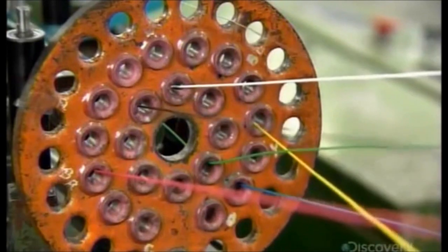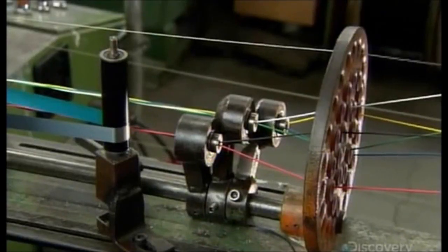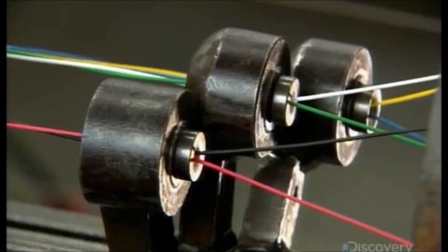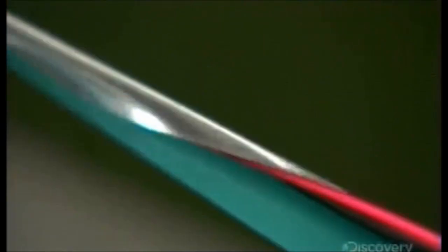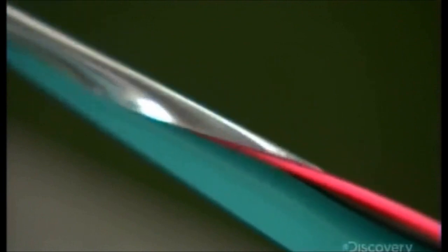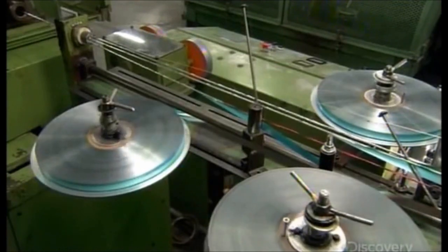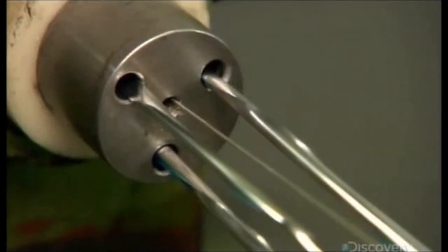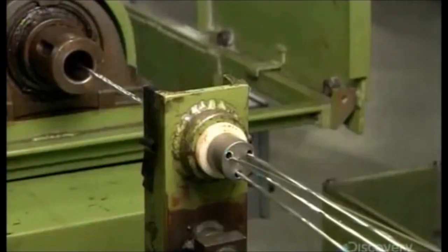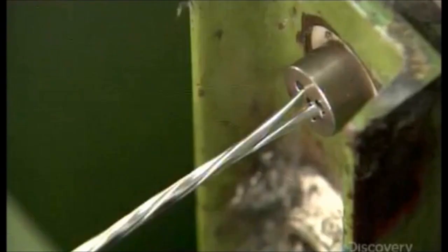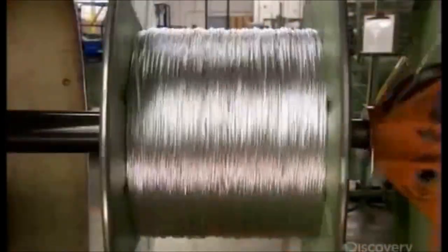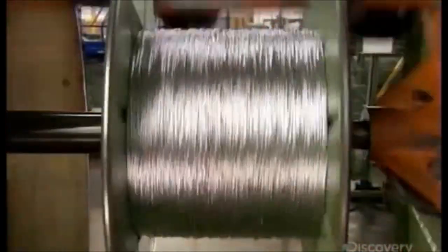Dies divide the 6 conductors of this cable into 3 groups of 2, twisting the conductors of each pair together. The machine then wraps each twisted pair in a shield made of aluminum-coated polyester. Shielding eliminates what's known as crosstalk, signals interfering with each other. The next die joins additional wires that don't need to be shielded to the shielded ones. Then everything gets twisted into one cable. Then a final twisting, seen here in slow motion. The actual speed is 1,000 revolutions per minute.